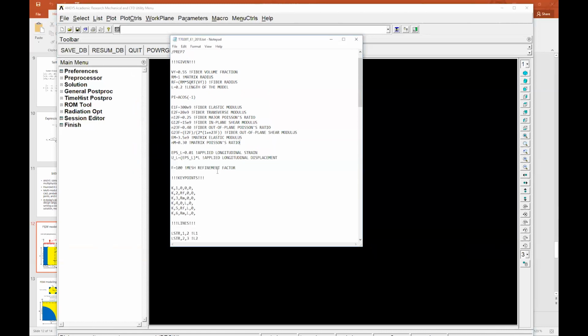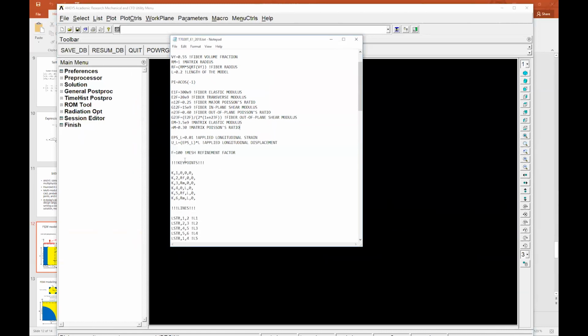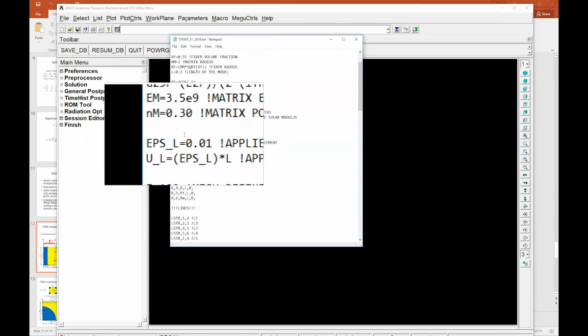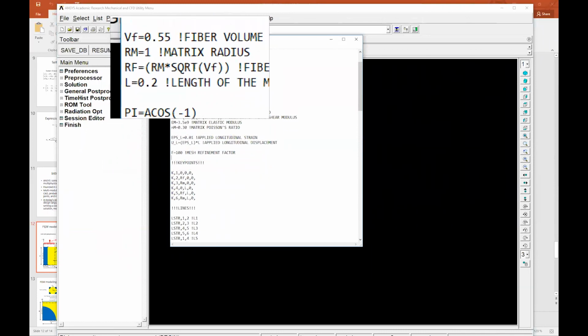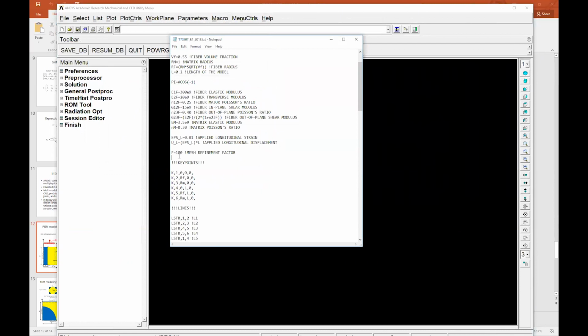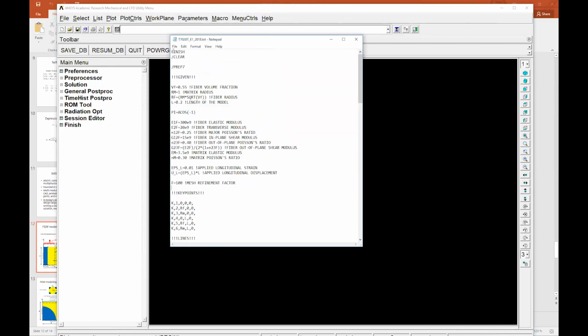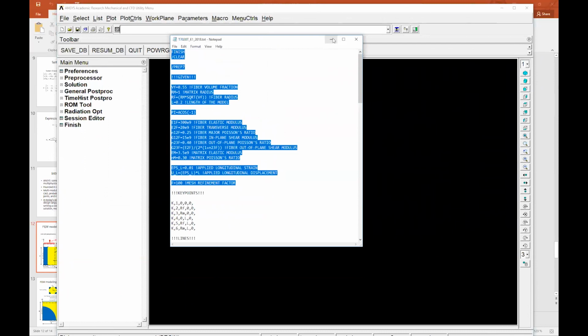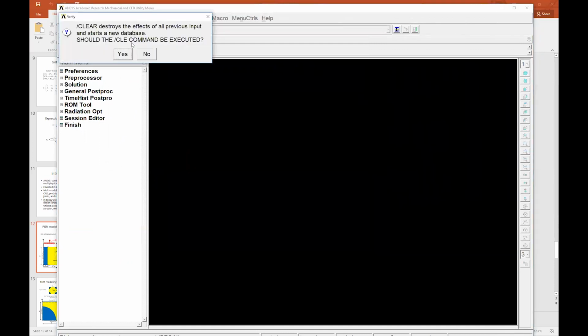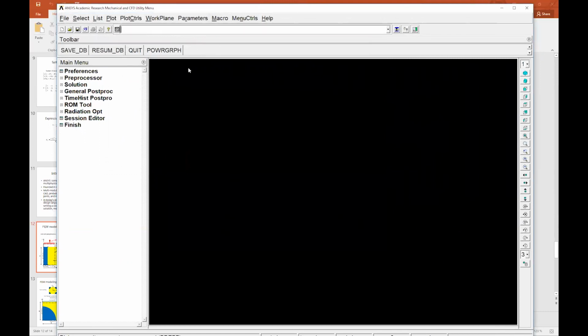Okay, so far we looked at the inputs, just given numbers, and also some simple mathematical expressions and how they are entered in this APDL language. You can, for example, also copy and paste whatever you want in the command window here in the interface. For example, I can just press Control-C, Control-V and enter, and it will read in the data, but nothing happened because we have not yet created any geometry. We just defined some parameters.